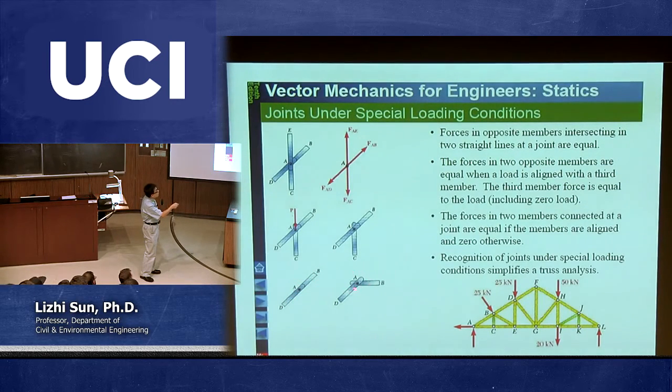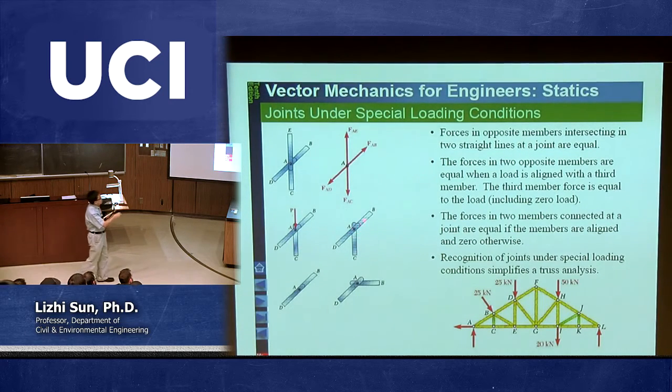If this is the case, then immediately you can say the internal force of AD and internal force of AB are both 0. That's called the zero force members, okay, if you encounter this case. The other case, which I want you to understand, is having 3 members connected with the joint, and there's no external forces. And among these 3 members, 2 of them are in one direction, in 180 degrees. Then the third member should have 0 force. So that means you don't have to cut. You can conclude the internal force of AC is equal to 0.